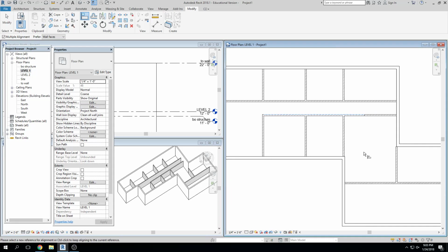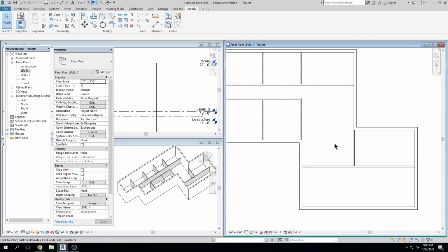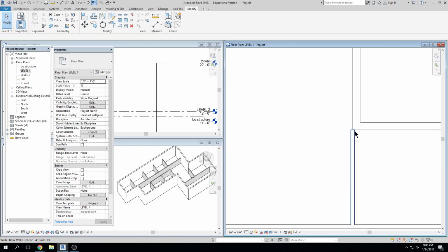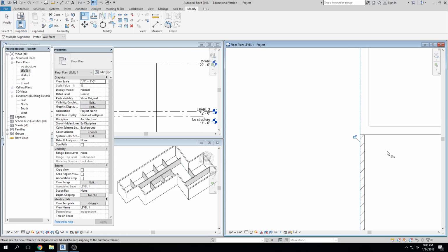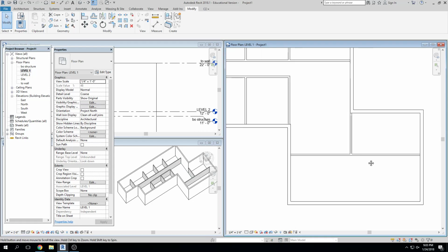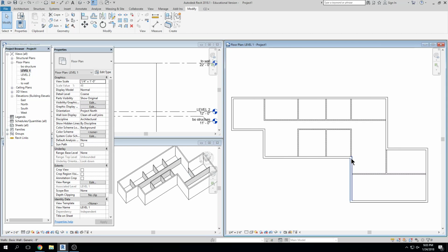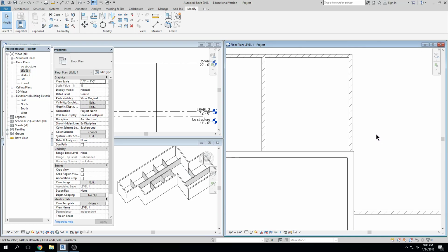right? Trim, TR, okay, but I probably don't need that. Click, delete, and oop, that needs to be aligned a little bit better. AL, click, click, okay. We don't have any doors or windows. Oop, there's another little one, AL, align, click, click. They line up very nicely, right?